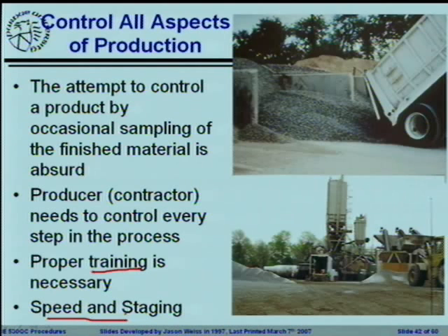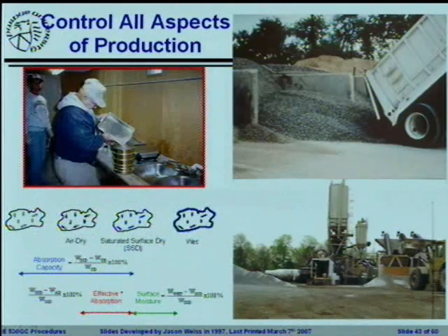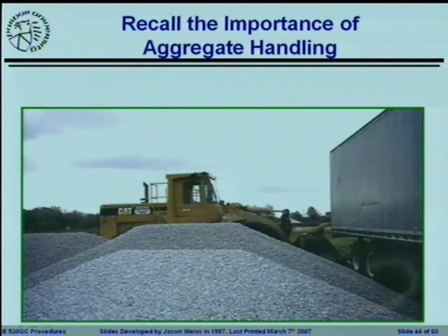It is very infrequent that you're going to be able to go into a large infrastructure project in the middle of a city and lay out all the materials that you're going to use from start to finish and work your way from one end of the pile to the other during the course of the job. You will find that people are trucking in materials that same day and dumping them straight into the plants. So controlling this is a very, very difficult process, and that's why we need to make sure that we've got high quality standards in doing that.